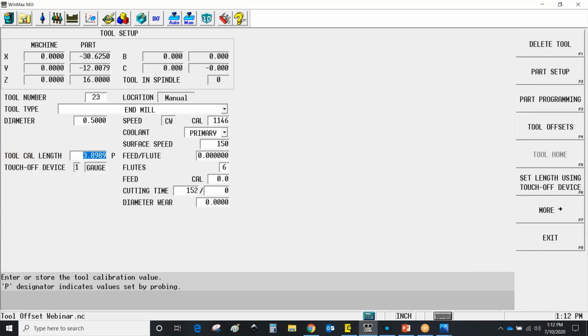Sometimes we're able to have 9,999 tools in our library. And sometimes people want to use tool 900 and they want it to be offset 900 and they want to be able to control it that way. Well, obviously our table only goes up to 200, both for length, radius, and corner radius. So if you have tool 900, you have no way of calling a D900.